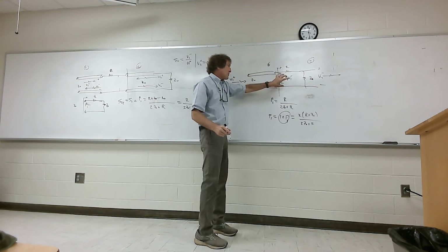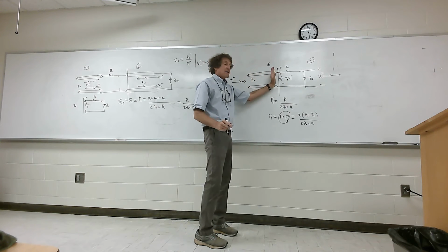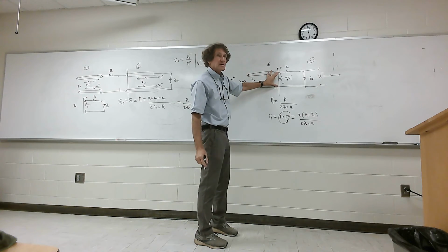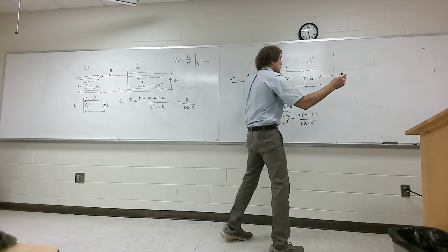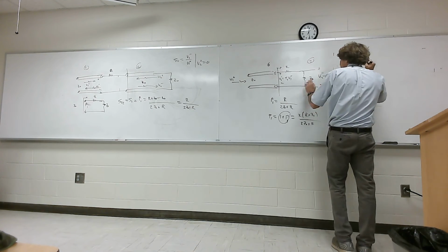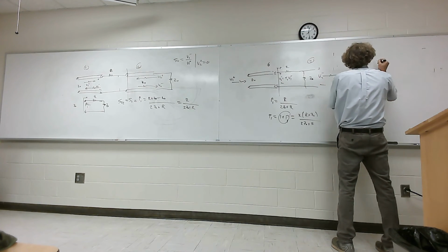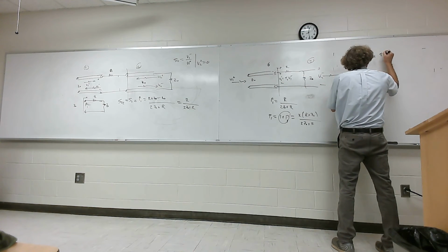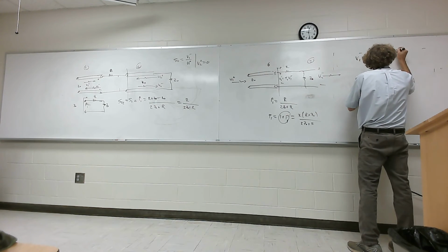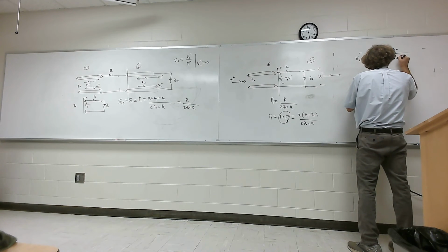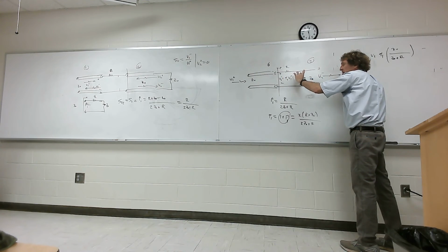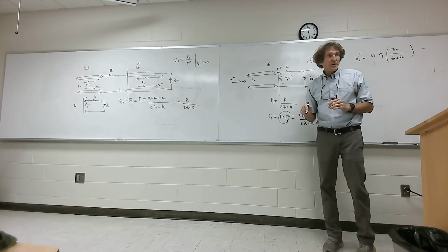Think about it. That voltage right there is not the same as that because some of that voltage is reflected back. Okay? But some gets through. Now the amount that gets through just undergoes voltage division. So we can say that V2 minus is equal to this voltage here, V1 times the transmission coefficient at port 1, and then times this impedance over Z0 plus R. It's simply voltage division. After you hop on here, the amount of voltage developed here is just going to be found using voltage division. Do you all follow me?